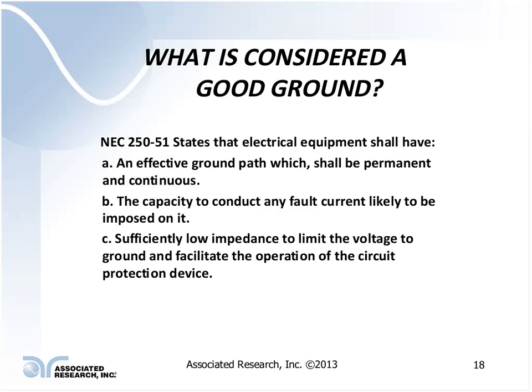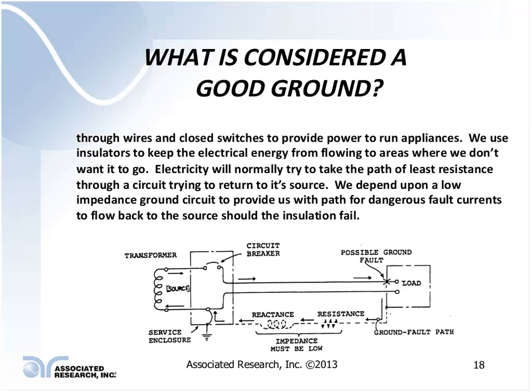The capacity of that circuit conductor should be large enough that it will allow my fuse or circuit breaker to trip off and shut off the potential going to the product to eliminate any fire hazard or any other potential shock hazard that should occur. So that's what that ground circuit is designed to do.